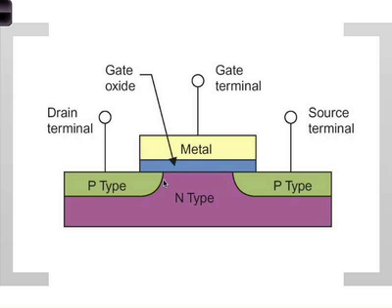You make a depletion region. And you apply more negative voltage. You pull the holes closer together to this interface. You create a P channel as opposed to an N channel before. So the logic is exactly the same, but the signs are all inverted. Okay, in this case, you have to apply a negative voltage as opposed to a positive gate voltage.